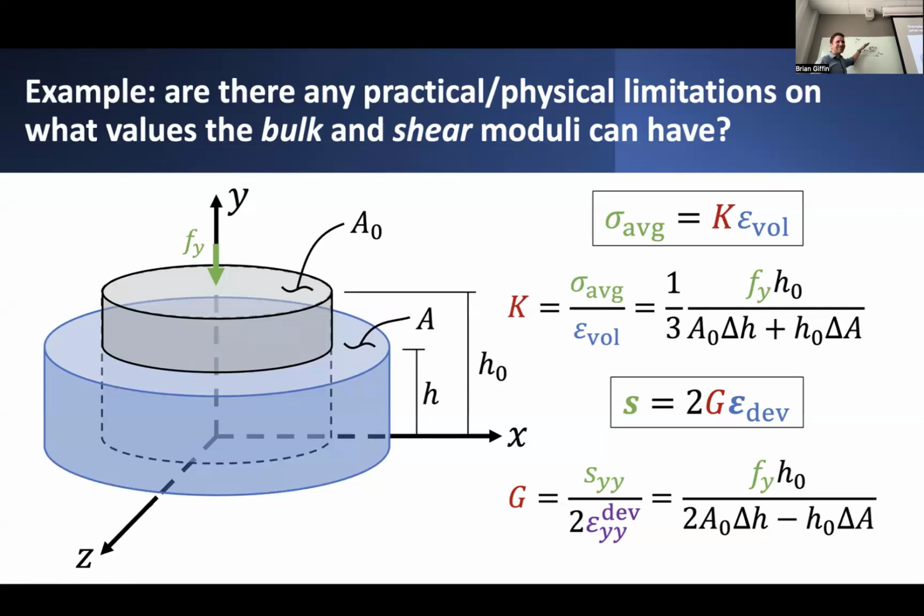The situation you would have with a negative slope in this curve would be that if you tried to expand some piece of material, it would actually generate some kind of compressive stress. Or conversely, if you tried to pressurize some sphere of material and pushing on it actually causes it to expand, that would be a negative bulk modulus, which makes very little physical sense.